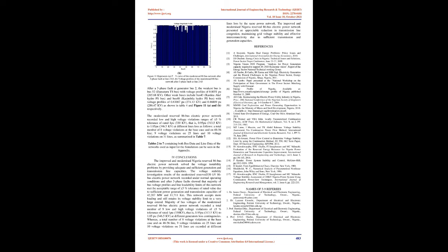Evaluation and deployment of reserve-based electric power resources into the Nigeria 28 bus power network. The overall integrity of the existing Nigeria 28 bus power network, in fast increasing population growth, is continuously affected by acute shortages of electric power generation and transmission capacities. The existing Nigeria 28 bus power network has as-built electrical generation and transmission capacities with detailed design parameters comprising 12,682 MW and 5,988 km grid and transmission capacities, 28 buses or nodes, 10 electric power plants, 18 load, PQ, buses, 16 equal numbers of single and double lines and 4 loops, as shown in Figure 6.